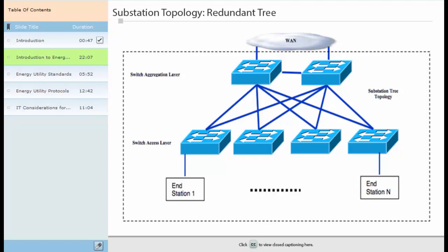Ethernet LANs can encompass multiple physical topologies, for instance redundant trees, stars or extended stars, rings or dual rings, and so on. Usually logical topologies are built on top of the physical topologies. For example, VLANs can be used to provide logical separation between IED devices. In the majority of modern Ethernet LAN deployments, a redundant tree topology is used. Such a design could be used to connect process bus networks inside a substation.